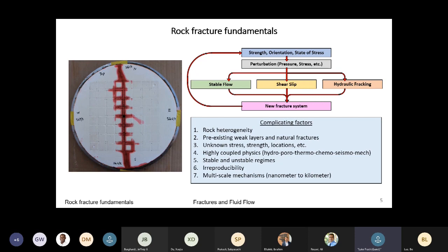Okay, so you have all three of these mechanisms potentially going on simultaneously with perturbations in the subsurface. It doesn't necessarily need to be the pore pressure that's connected to the injection well that's causing these effects. It could be remotely triggered. And it can even be remotely triggered by things as seemingly far-fetched as distant earthquakes or moon tides. So it's good to remember that these kinds of mechanisms can be happening on an almost continuous basis in some places.